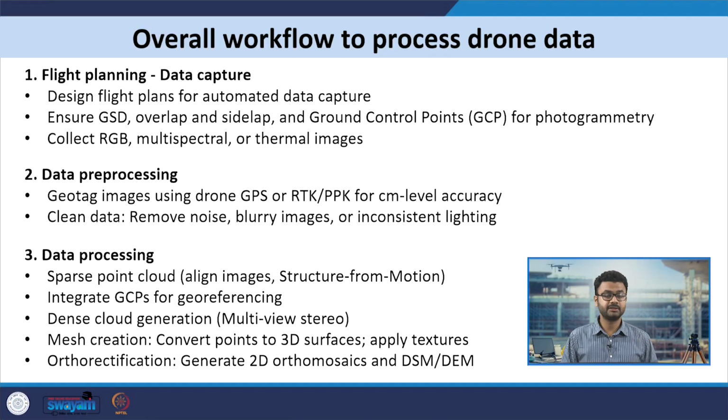Welcome back to our course on drone surveying. In today's lecture, we are going to focus on the various software to process drone data. As you know, when we are trying to process the drone data, there are three major stages. There is the flight planning and data capture stage, the data pre-processing stage, and the data processing stage, by the end of which we get our 2D orthomosaic or digital surface model.